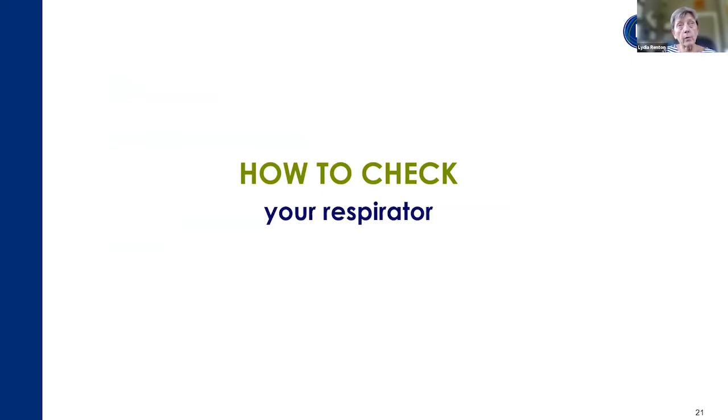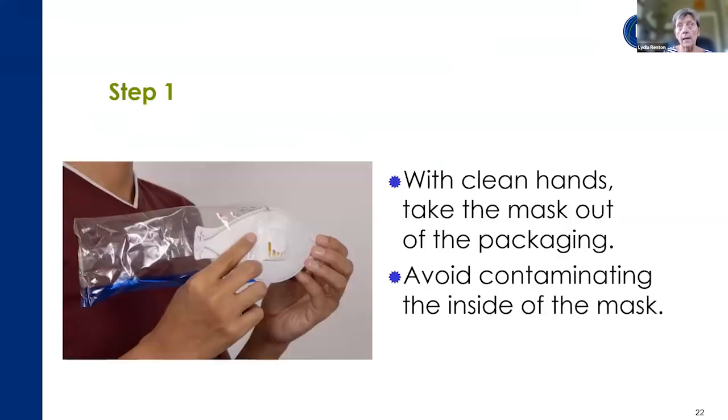Another very important component is checking your respirator. So you may be fitted on it, and you put it on your face. But how do you check? You had it fit tested a week ago or a month ago. How do you know that it is still okay?